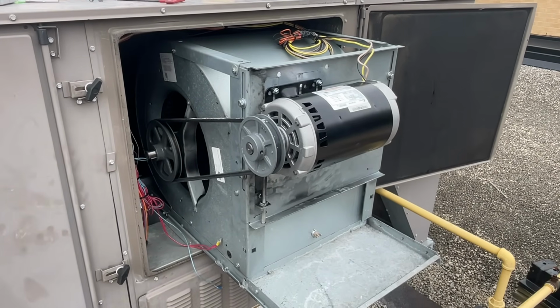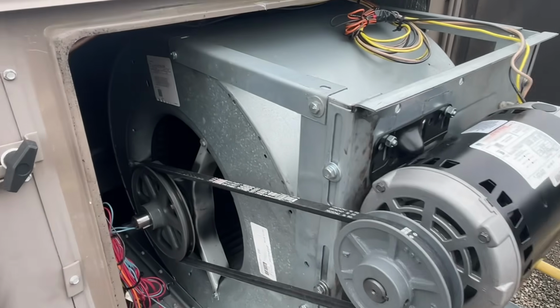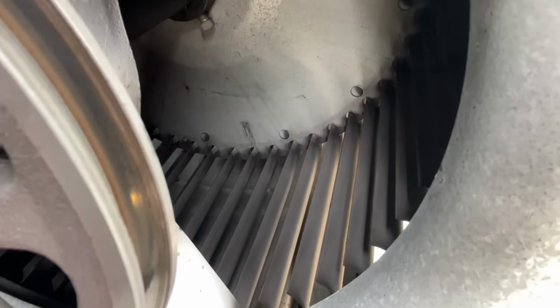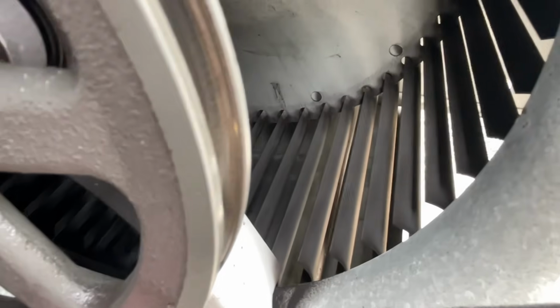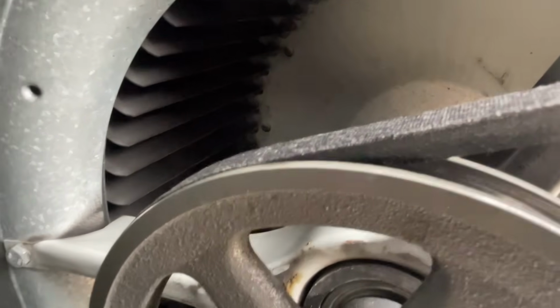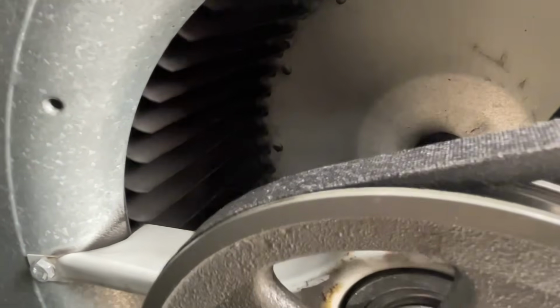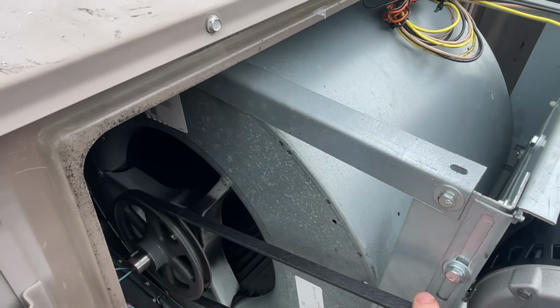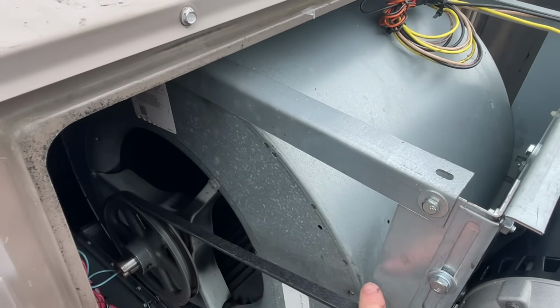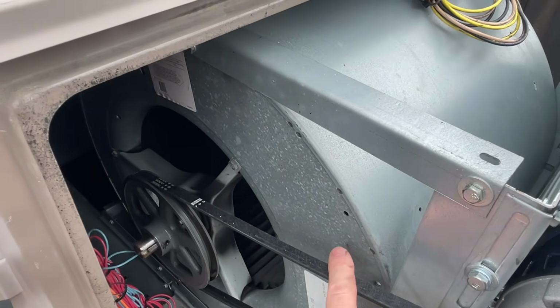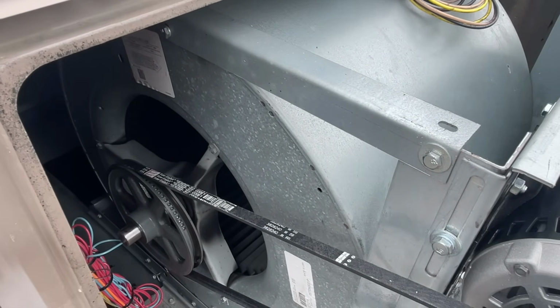And just to be more clear on airflow, if you guys are new and you're not that comfortable with the positive and negative side of the unit yet, you can also use these squirrel cage or blower wheel vane curves here. So I'm trying to get a good shot. Can you see how it's curved this way, not this way? So our correct rotation would be this way, because we're going to want to scoop the air. So that's another way you guys can double check if your fan is going the correct way.